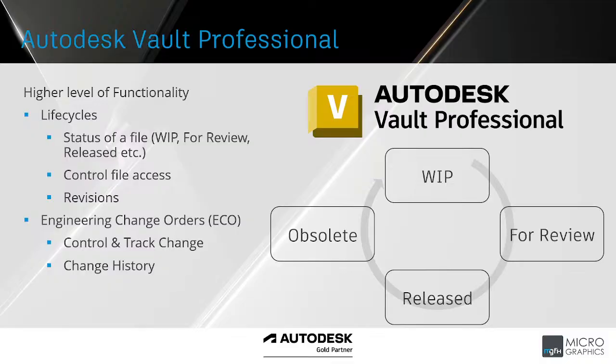Then going up to Vault Professional, it's got all the Vault Basic functionality and more. So it's a higher level of functionality within the software. From an automation perspective, Vault Professional has API that can be tapped into for those custom applications. But built into the software, we also now have life cycles. So life cycles allow for the status of a file to be shown. Is it currently work in progress? Is it for review? Has it been released to manufacture? And each of these life cycle states can control access to the file.